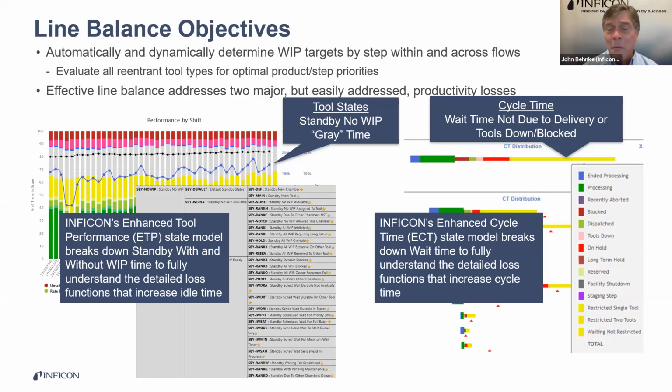We create a demand profile for all of those 15 layers, and then use that to drive the allocation of the utilization of that litho tool to improve linearity. That's happening nonstop for every single tool in the factory, of which there is more than one. And that's the beauty of a true optimized, scheduler-driven line balancing algorithm.